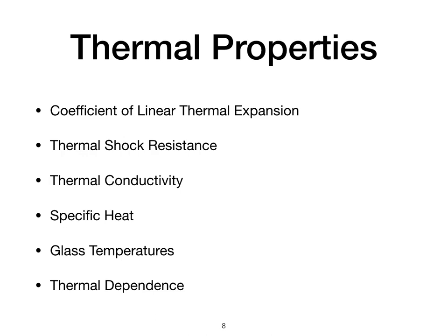It is often tested by taking heated glass lenses and rapidly cooling them through methods such as immersion in an ice bath. This type of testing can indicate the ability for glass lenses to withstand large changes in temperature when installed in applications. Glass lenses used with high power lighting can be exposed to a lot of temperature changes, and experience rapid cooling when exposed to rain, snow, or other environmental factors also. Next is thermal conductivity.